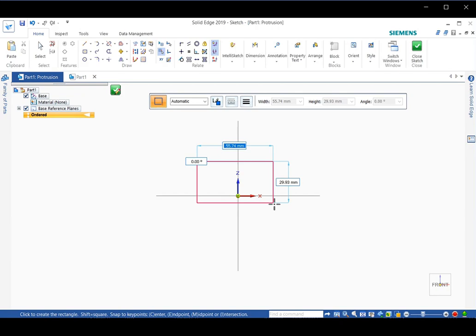This allows you to enter a dimension, for example, 50 here, and press the return key, the Enter key. Then the next box will be highlighted. Here we can enter a different dimension, for example 30. Then you press the Enter key. That dimension will be fixed.